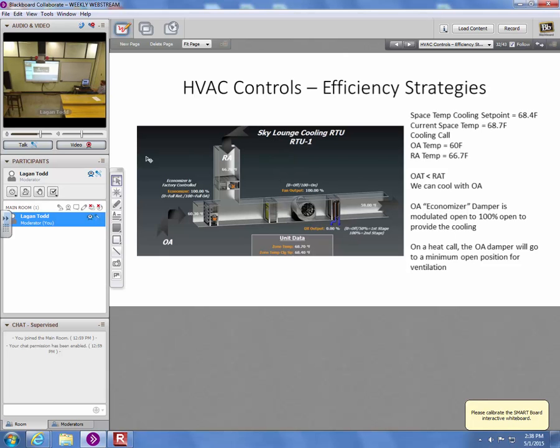So here's an example. This is, again, a screenshot from a building automation system, different project. This is a packaged rooftop unit. I should have put a picture of it in here since they don't look anything like the schematic, but it's just a big metal box sitting on the rooftop. It has an outside air damper with a little electric motorized actuator on it, as shown schematically here. It's got a return air damper with its own actuator. It's got a fan, and a direct expansion AC coil for air conditioning. This is a cooling-only unit. There's no heating coil in it. This is a filter bay over here.